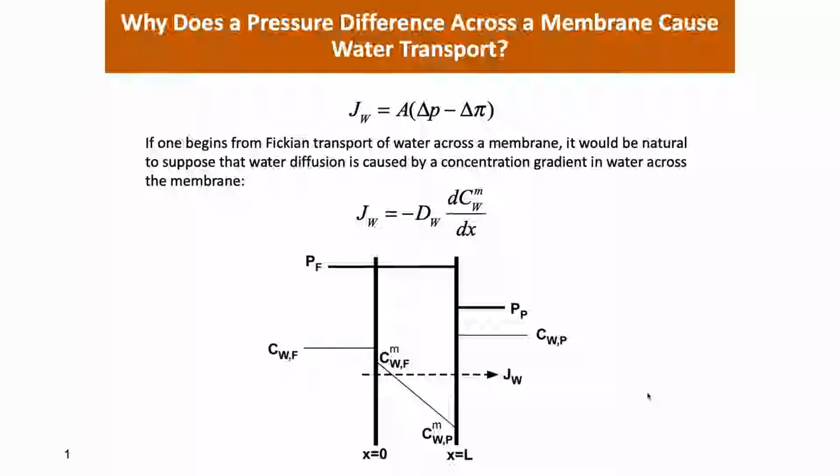One of them being organic solvent nanofiltration, where instead of distilling, say, mixtures of benzene and cyclohexane in order to separate them, you can put them in contact with a solvent-resistant membrane and use pressure-driven transport in order to bring about that separation. And thereby you avoid the phase change and the energy penalty that you normally find in distillation. And so this is an area where there have been a number of startups formed. I don't believe there are any